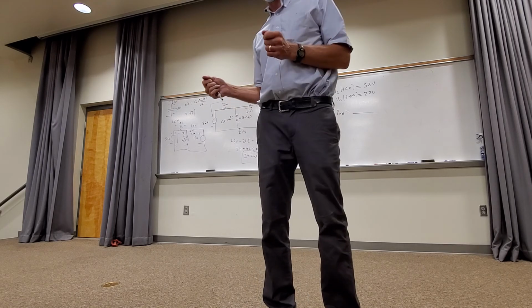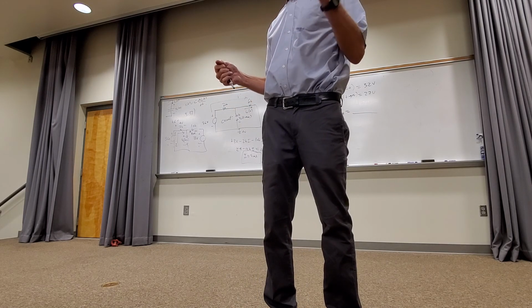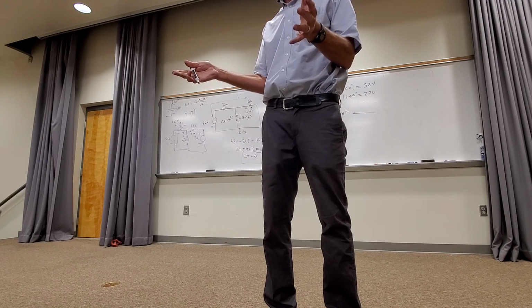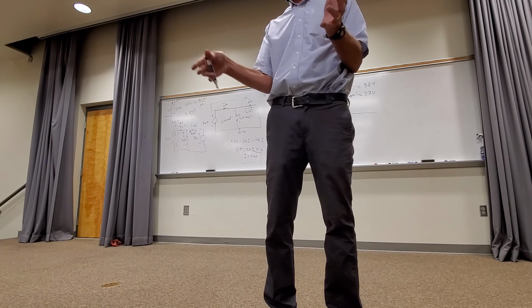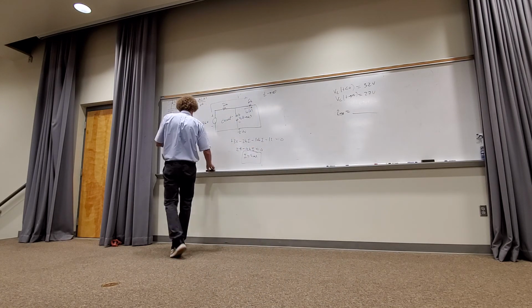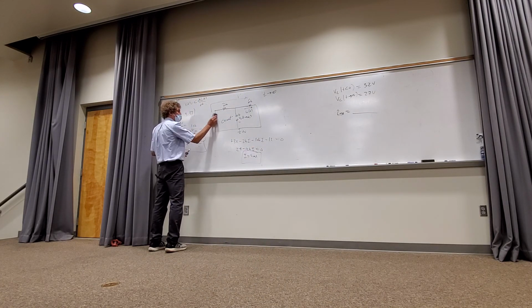What do we do when we want the Thevenin equivalent resistance between 2 points if there is a source? Yeah. You short the voltage source. Yeah, short the voltage, open the current. Y'all remember that? Current sources become open circuits, right? Voltage sources become short. Y'all remember that? So if that's a short circuit, I'm going to short it right here because I'm about out of time.